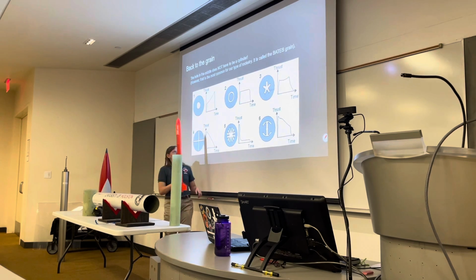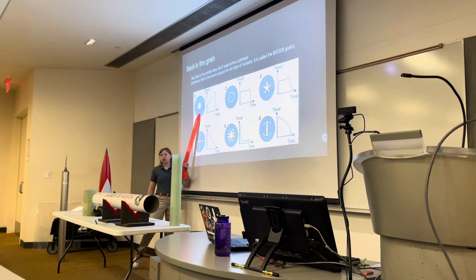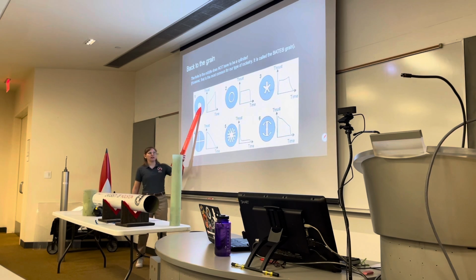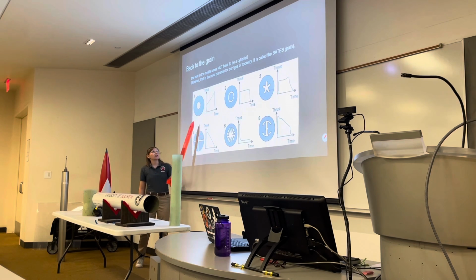This is your most standard rocket motor grain. You're not really going to be able to use any of these unless you make your own motor and you're like, hey, I want to use a double anchor. Most standard commercial off-the-shelf motors are going to use this Bates grain. Something curious about these you can see as well, though, is that different grains give us different characteristics.